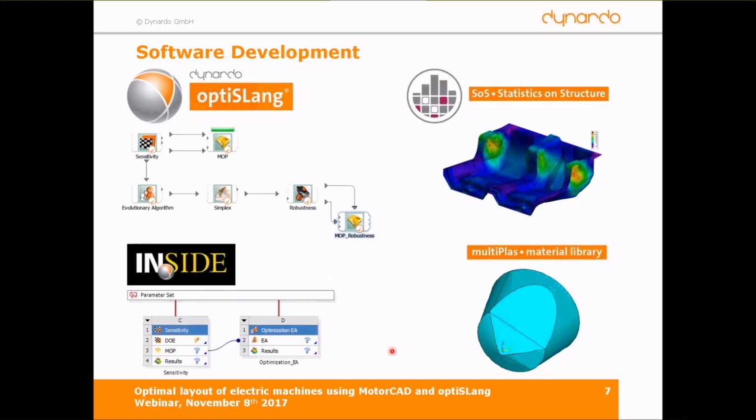And what does it mean, real-world capability, for example, handle failed designs, handle lots of parameters, handle noise, things like that. So this is how we develop optiSLang, the software you use for driving design variations and analyzing how the outputs are varying, sensitivity study, metamodel-based sensitivity study. And if you use the math for the scalar responses in optiSLang and you generalize it to field outputs, this means you take into account if 2 outputs are correlated.